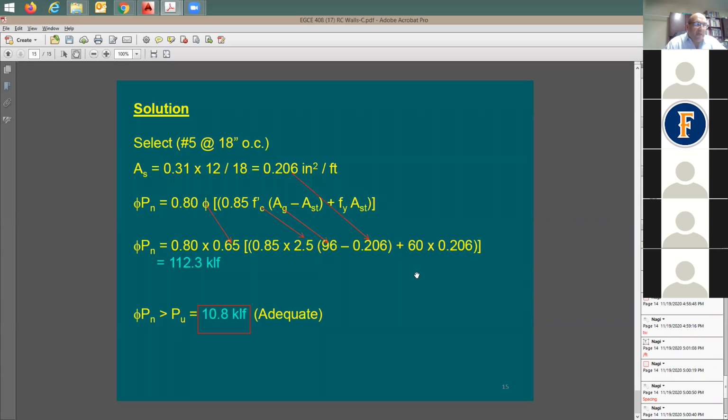When it comes to a reinforced concrete wall, whether it's a gravity wall or a shear wall, you usually have lots of capacity in axial load forces. So when it comes to axial load, you have plenty of capacity, and you shouldn't have a problem. Use the minimum reinforcement to be able to make it work. Unless you have many stories, right? It's going to be a different subject.